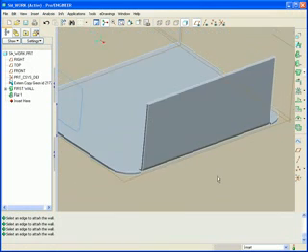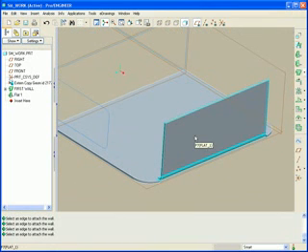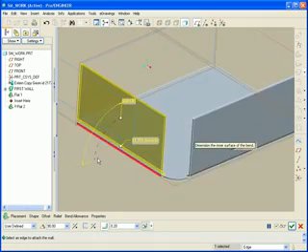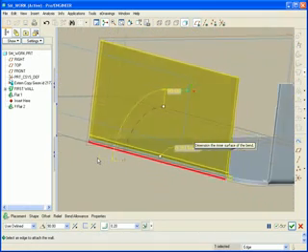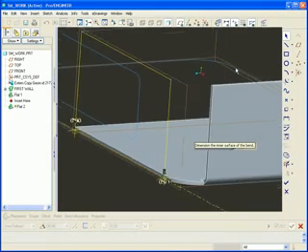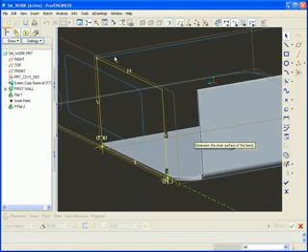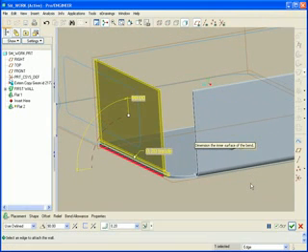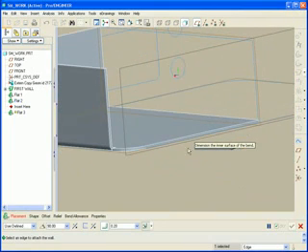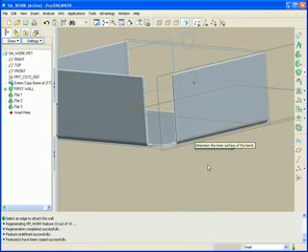Now let's take advantage of this. We've already developed this wall already. Why don't we just copy it? So we'll just copy this one, and then we'll be able to paste it. Control V, picking then this edge. Okay. Notice the shape already is locked into that same vertex. So Control C, Control V, and then we'll pick then this edge, middle mouse button, and then that wall is finished as well.